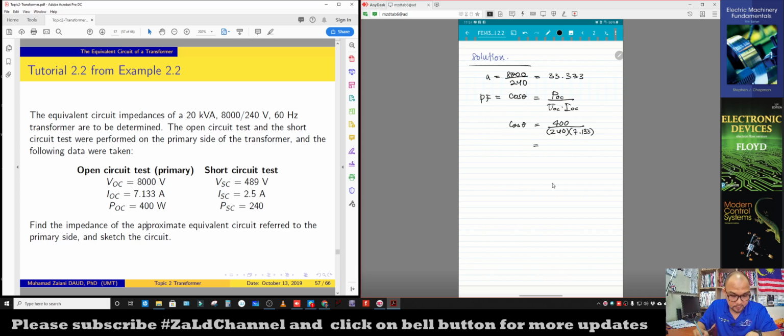So finally we get the power factor, which is PF equals 0.234. Let me just fix it to 4 decimal places. So we have the power factor. We know that the angle for an inductance-based element is always lagging. All right, so this is power factor lagging. For the capacitor, it will be leading, right?